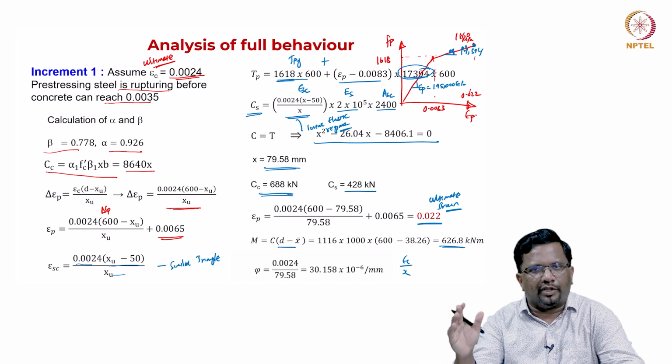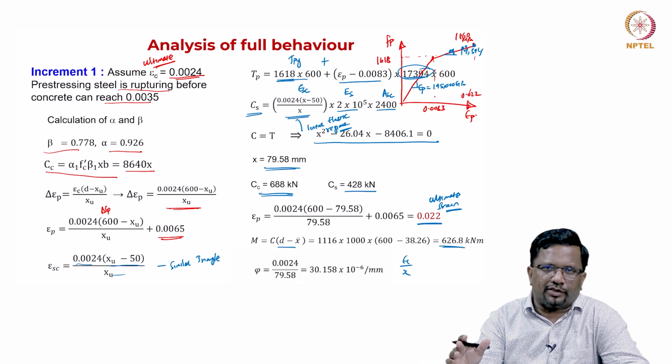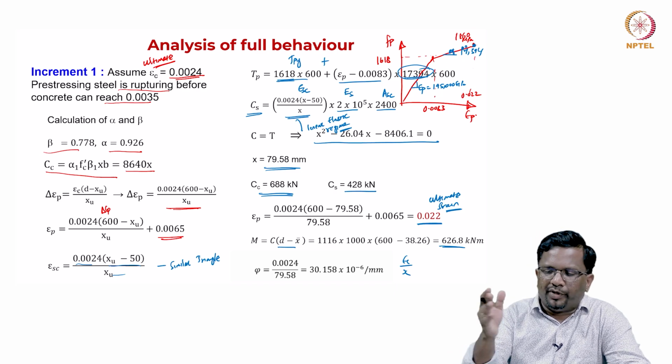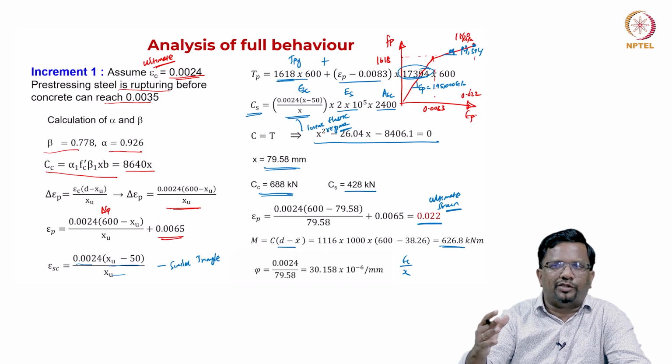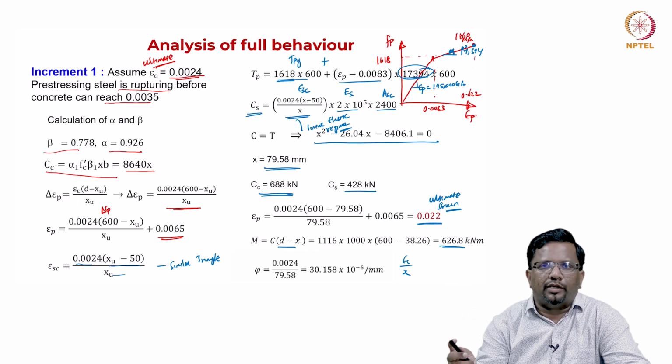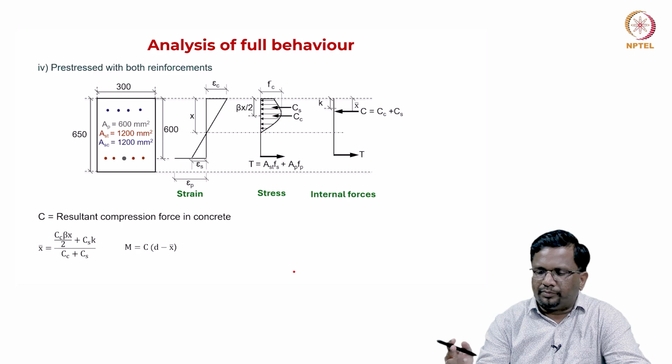So like this we can calculate for different sections. So this is for the ultimate condition. Again, for previous initial strains of different epsilon C, you can also generate the moment at curvature, and you can generate the entire moment versus curvature response, right.